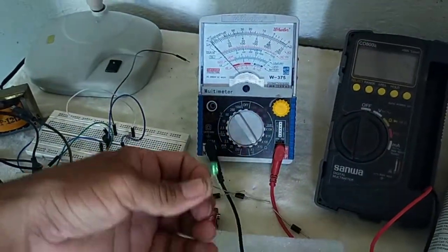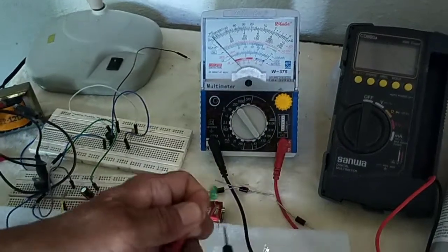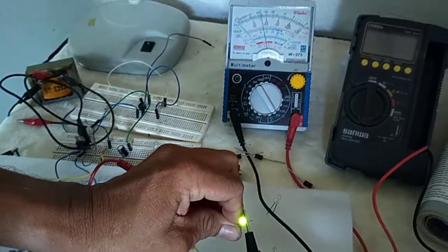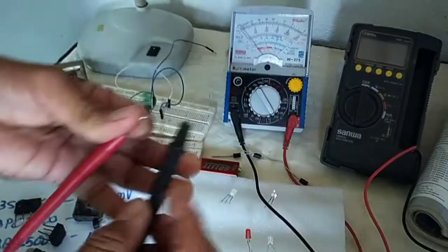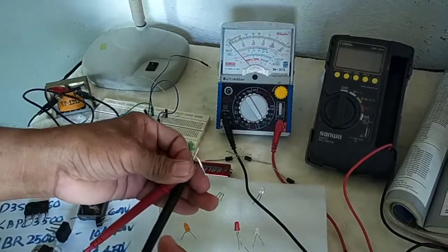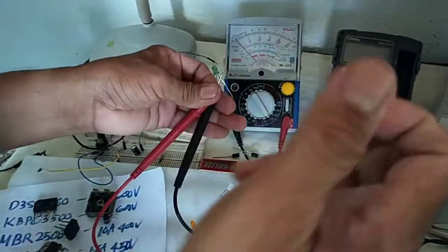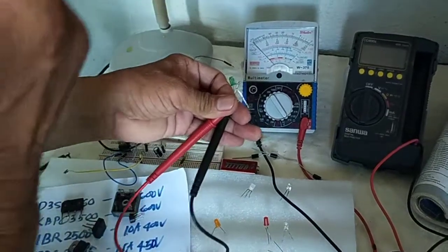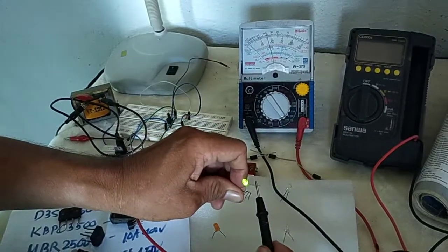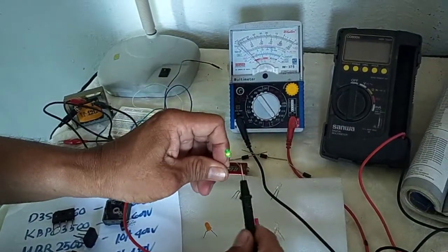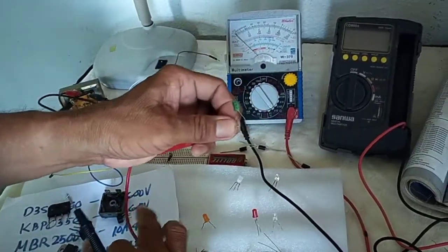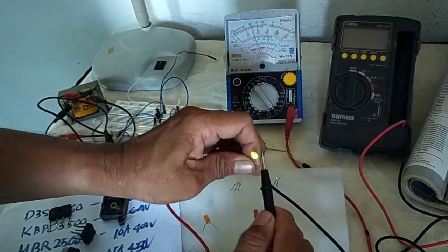No deflection, reverse bias. Deflects. Then it lights. So we need to say the electrical energy or the current is circulating around the diode because it is forward biased. So that current is actually the electrical energy. It is then converted into electromagnetic radiation or light. Forward biased. So this should be the anode and this should be the cathode. Cathode because this is negative for the emitter, and anode, forward bias.